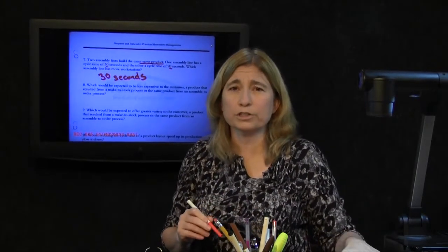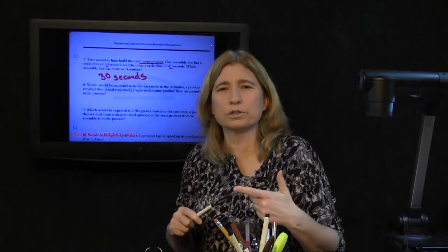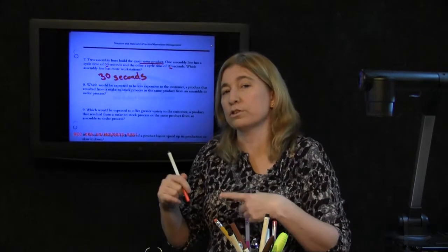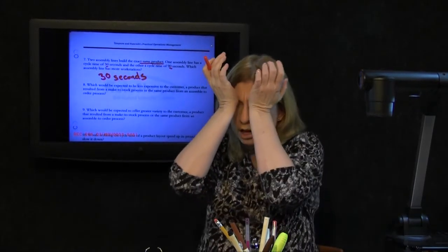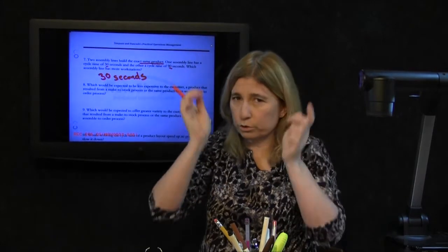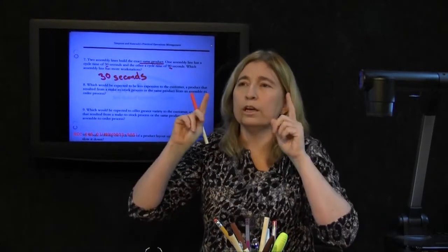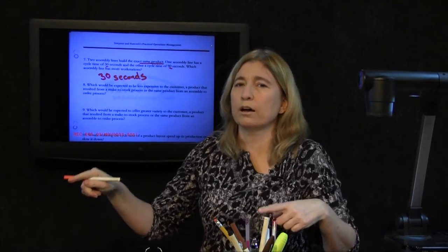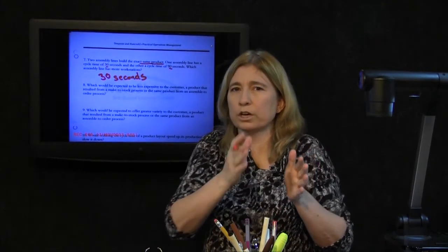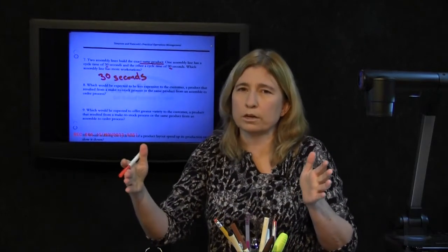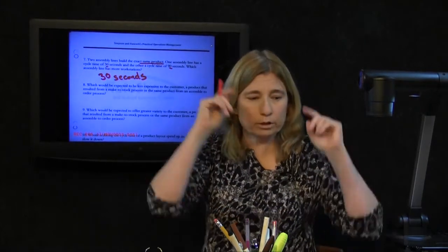more workstations. That's actually going back to the other question we were looking at, like the 15 versus the 20 workstations in the previous question. Anyway, the shorter your cycle time, the more workstations you're going to have. The longer your cycle time, the more work you can give each workstation, and thus the shorter the assembly line is going to turn out to be. All right, next question.